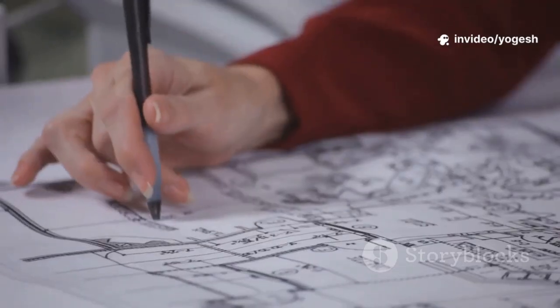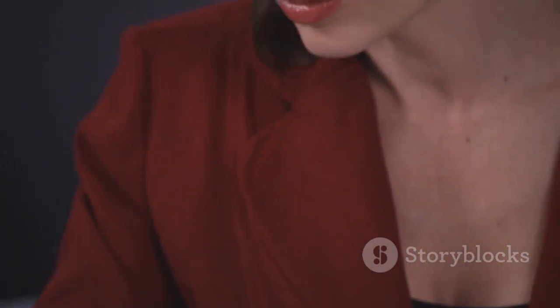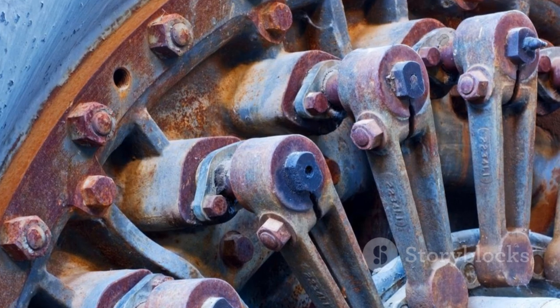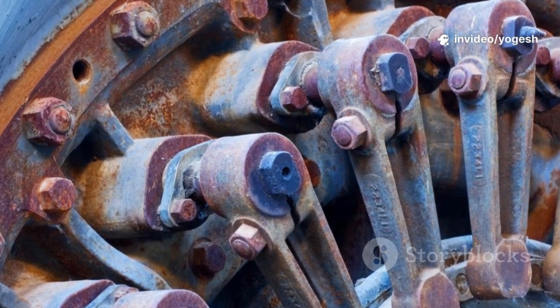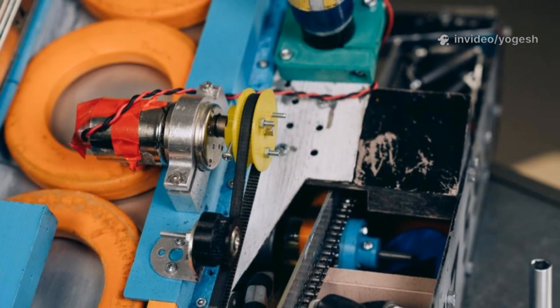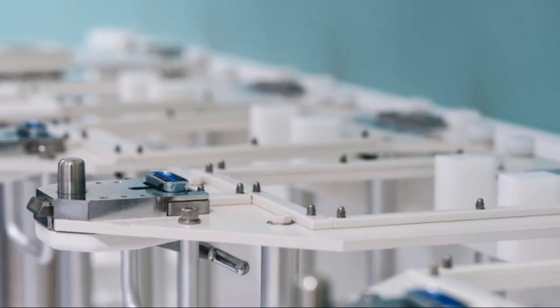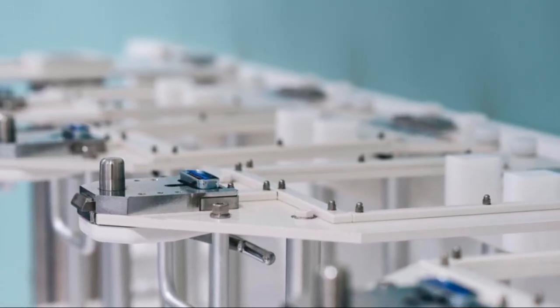Part drawings are incredibly rich in detail. Every feature, hole, and surface is precisely defined, leaving no room for guesswork during fabrication. Assembly drawings, on the other hand, focus on identification and organization, featuring a bill of materials and balloon callouts that link each part to its exact position in the final product.